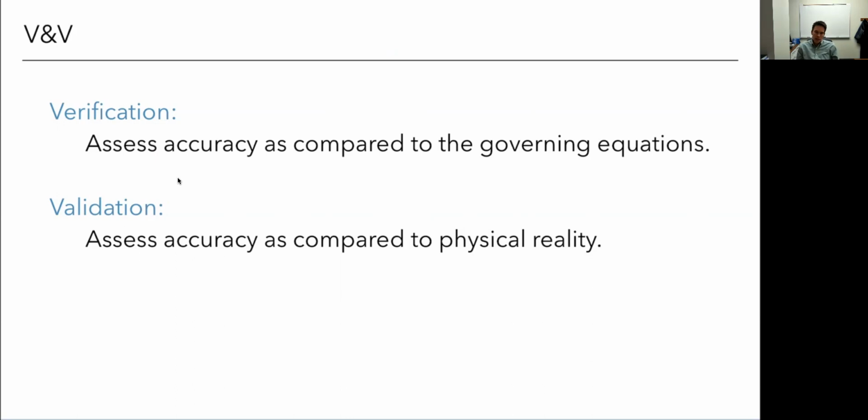So for verification, I guess in a CFD sense, I would consider it at least doing the grid convergence study. If you have time or an unsteady simulation, you also have to do a temporal convergence, maybe a boundary. The only time we do boundary refinement is if you're trying to be aggressive and shrink your boundaries because you're really doing a huge simulation, but typically we just make them really big. I guess another way we could do verification, I shouldn't say we don't do verification on CFD, because while you know the equations are being solved correctly, you don't know that you actually have put in the geometry properly and done the right boundary conditions.